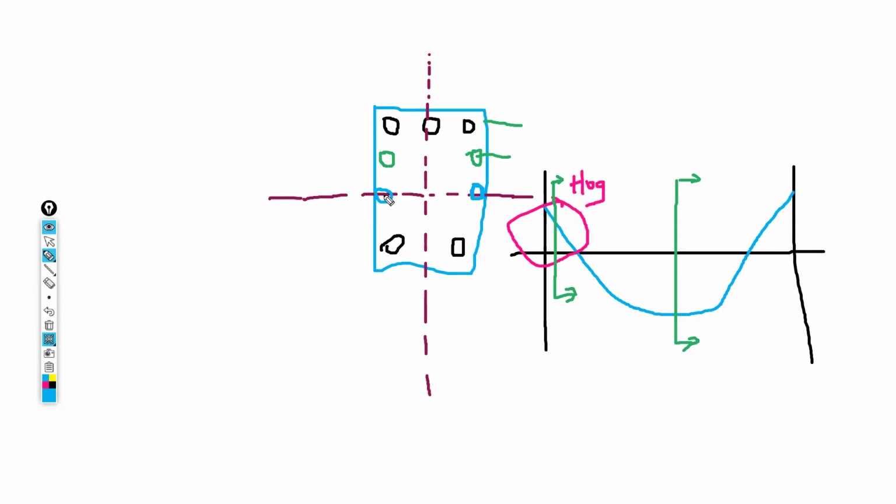And also if you misinterpret this cross section, and instead of having these bars placed at this point you place them at this point, you have made a very big error, because at this point we do not have moments. Okay, we don't have moments here at the neutral axis. So whatever you are suggesting to have layers of reinforcements, place them above or below the neutral axis,